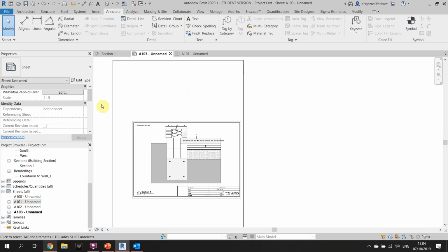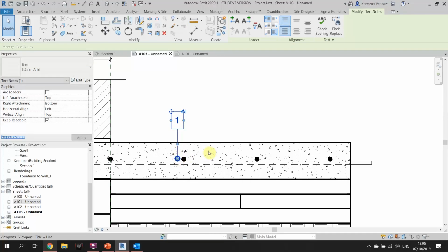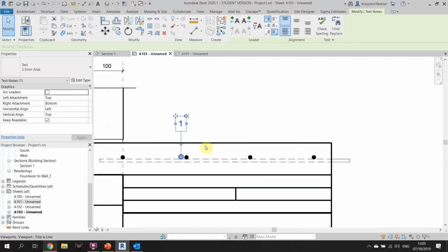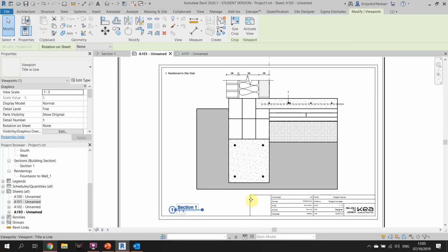They should not cross each other, at least if it's possible for them to not cross, because it can create confusion. And make sure that the object they point at is clear, that the annotation is pointing at the slab, instead of, if you just put it somewhere here, you could be confused whether it's pointing at the reinforcement or the slab. So make sure that they are accurate. It's the same way with 2D as 3D. You might put a key indicator to show where it's placed and how it's placed.